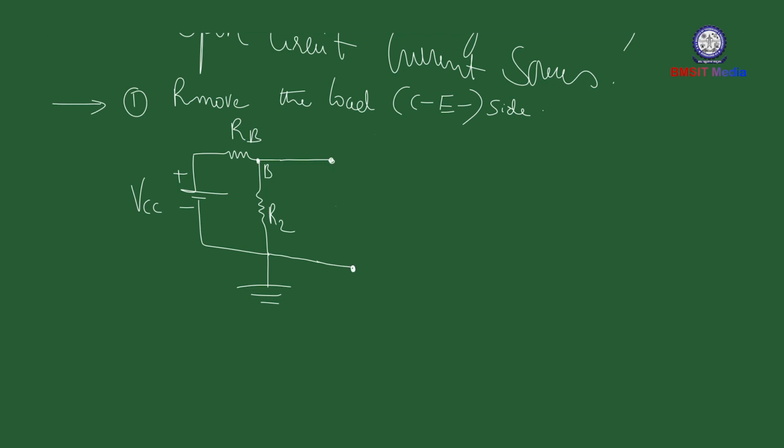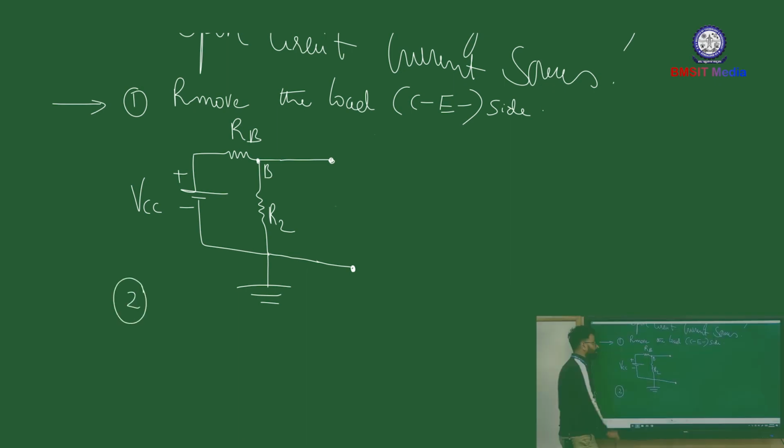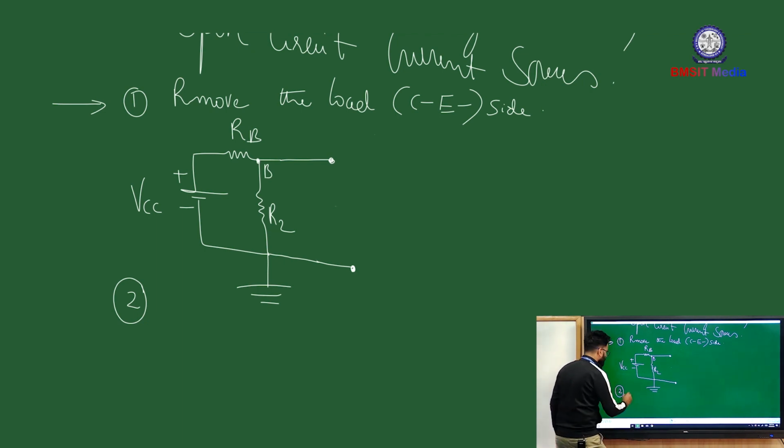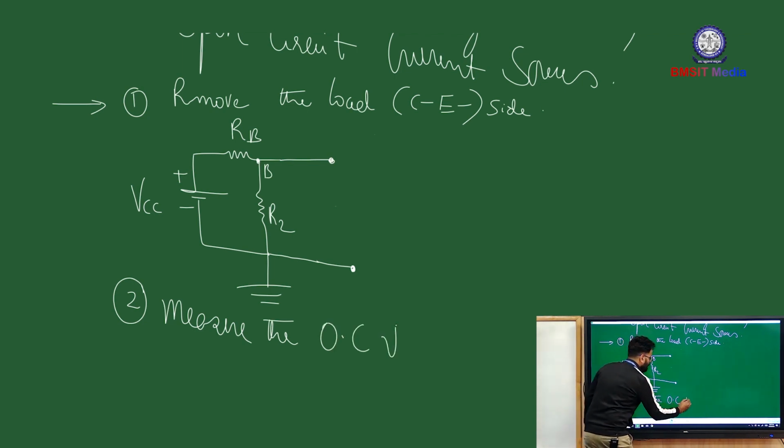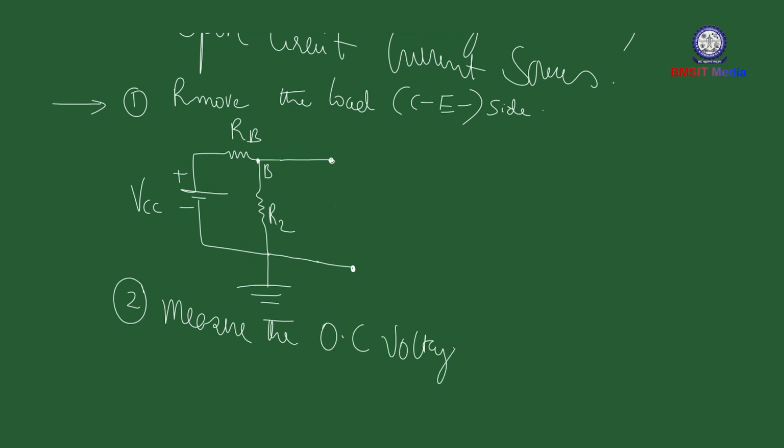After removing the load, you can apply step 2. Step 2 is to measure the open circuit voltage across the load. Where is your load?